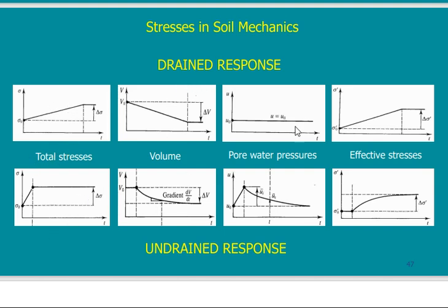Here is the volume. Here is the pore water pressure. Here is the effective stress. So start with the total stress. If I start at this point, the start here should be similar to the start here. But here I reach the maximum at a very long time, but in the case water is not leaving, then I reach the maximum very quickly because no compression happens to the sample. Then the full sample carries the stress very quickly.